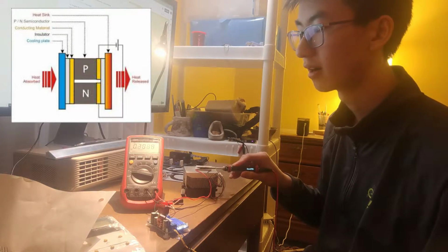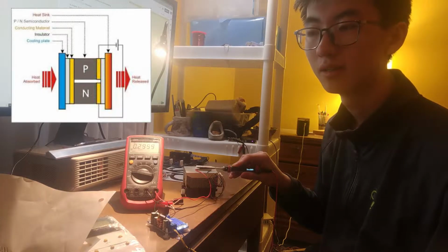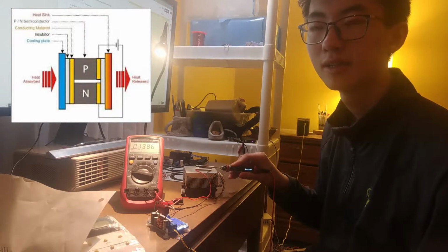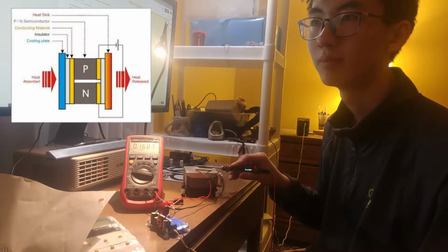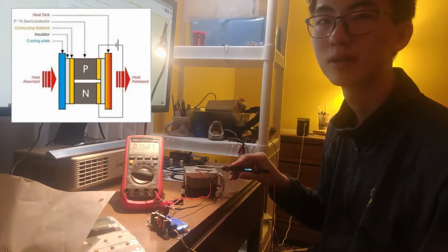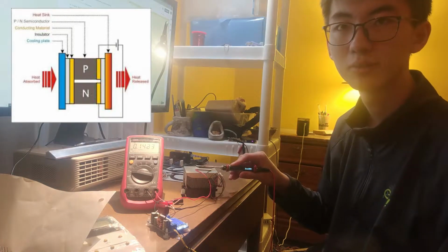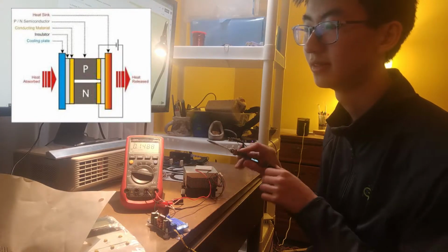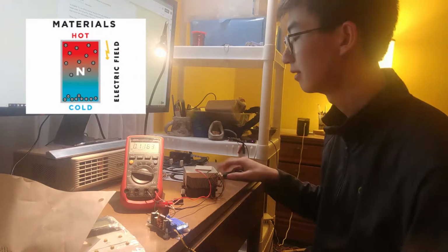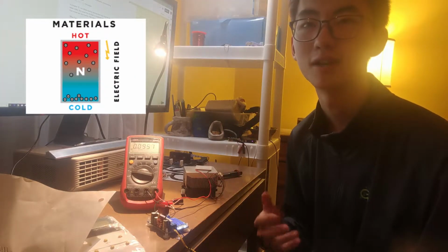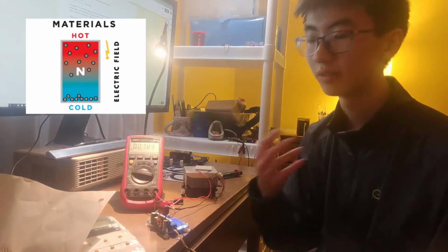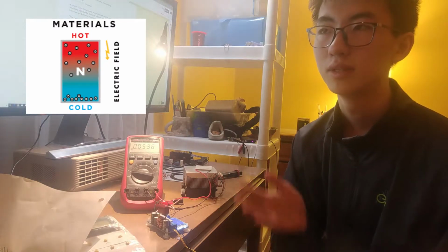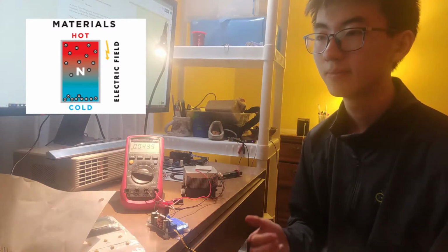And inside of those plates are bimetal junctions, which are essentially two different types of metals joined together. When heat is applied, the electron activity of the different metals will rise differently, and the differential between the two metals will end up being a voltage, as it is displayed here. And this reaction is also reversible. So if you put in voltage, it pumps heat, and if you allow heat to travel through, it provides voltage.